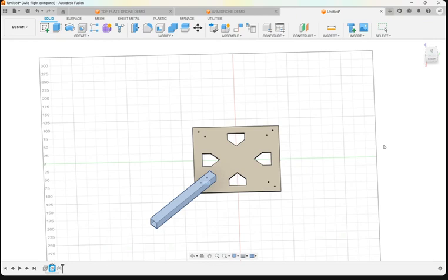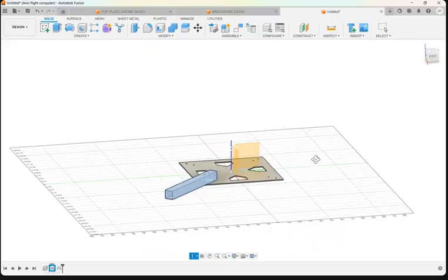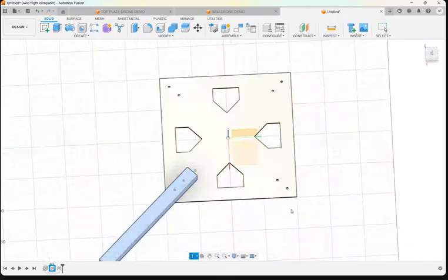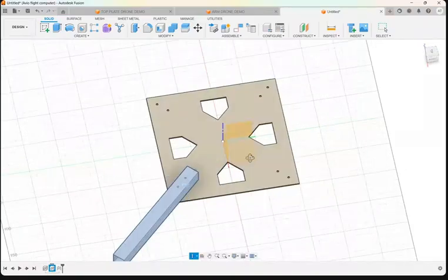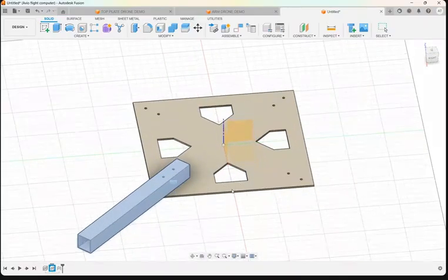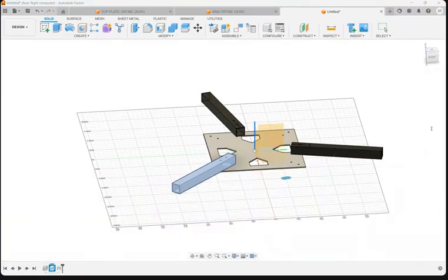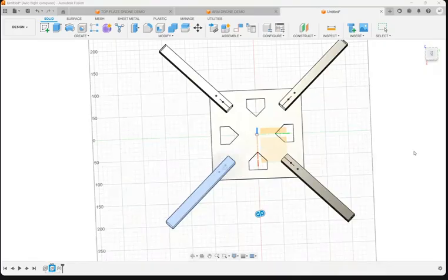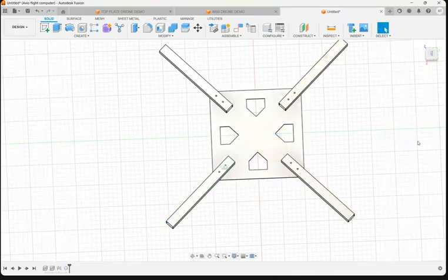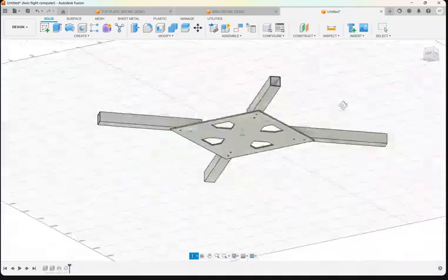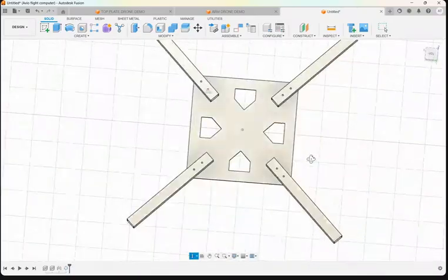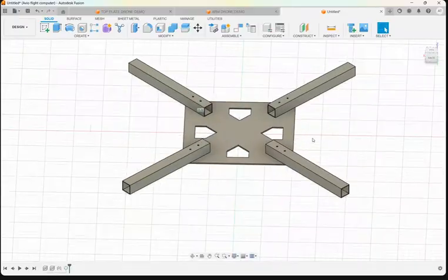We'll select the arm. We'll select the axis. Now in 3D we are selecting the axis, not in 2D. In 2D what was it, we used to select a point. Now because it is in 3D, we have to select an axis. So we will select the Z axis and we'll click 4 and okay. So now 4 arms are placed at this point.